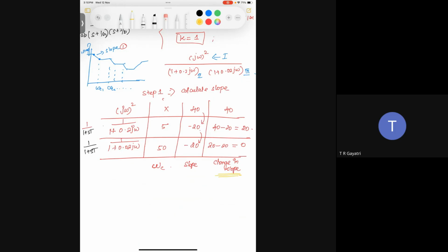No, ma'am. So what we are doing is basically first figuring out where each component of the transfer function is going to trigger, that is the corner frequency. Then we are calculating the slope based off the general forms we had, and then we are subtracting or adding the slopes respectively. Yes. And then we are going to find the magnitude at that particular corner frequency. That's it. If we connect all those dots, we will get the Bode plot.